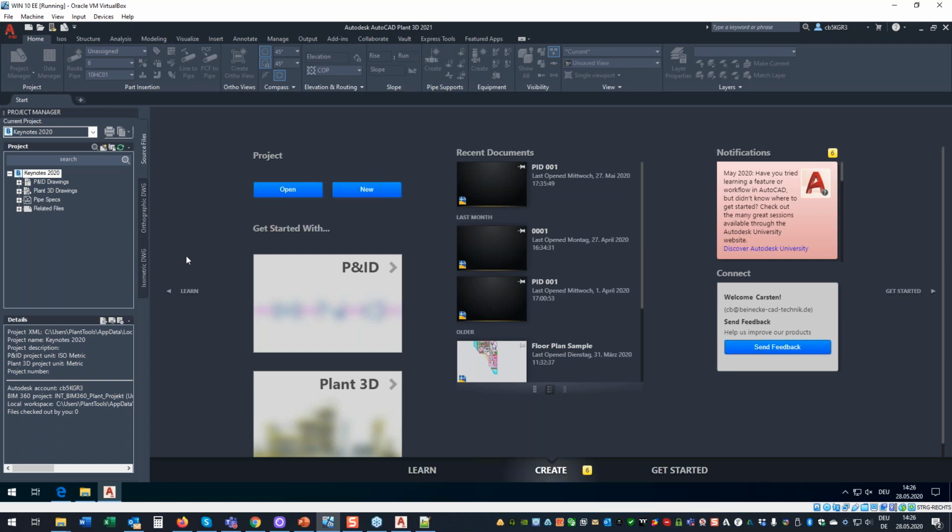That would be perfect. Then I could start Plant Data Manager and open the project from BIM 360. That's possible, but I need to start that command to download the data as well, because there is no API for that. What I'm doing here, opening a collaboration project, everything that happens then is done by Autodesk for Plant 3D specifically, and I'm not aware that there is an API which we can use.